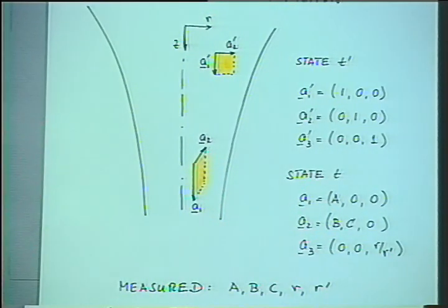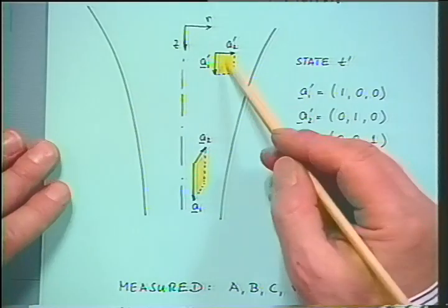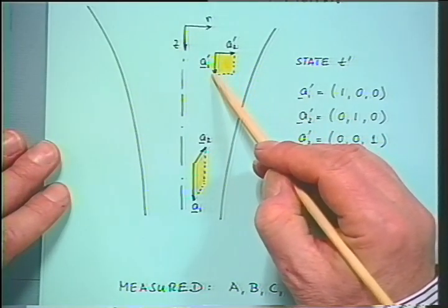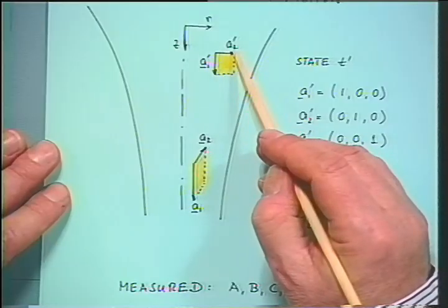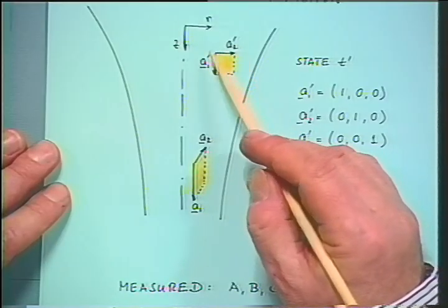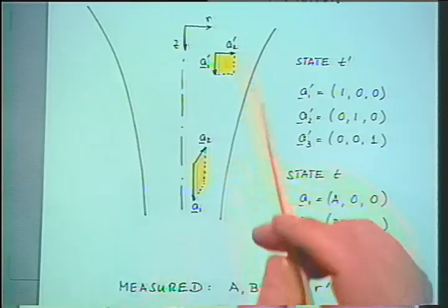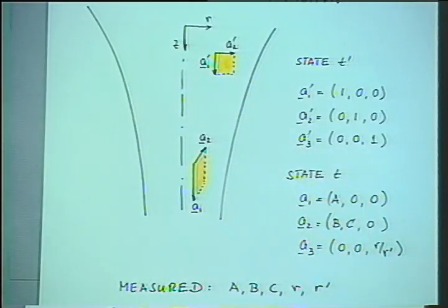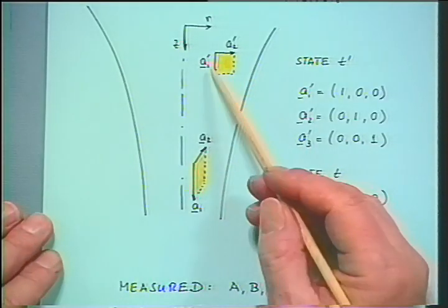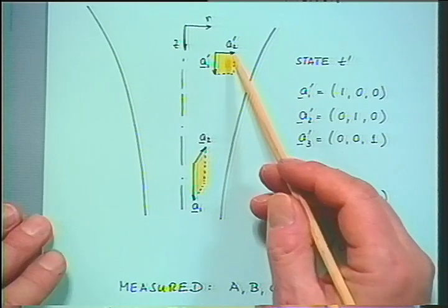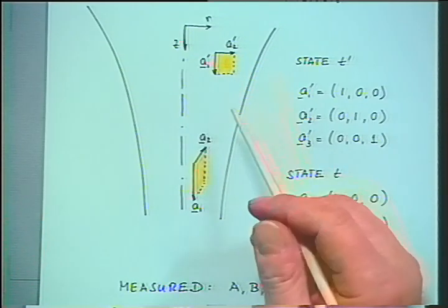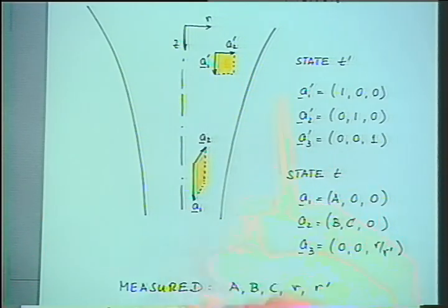Now, remember how do we describe a flow? We need 3 independent material vectors for a complete description of that flow. Let's pick A1, a material vector in one direction, A2, a material vector in radial direction, and then A3 would be a material vector in hoop direction. If we know A1 and A2, then we can calculate A3, or vice versa. They are connected by conservation of mass.